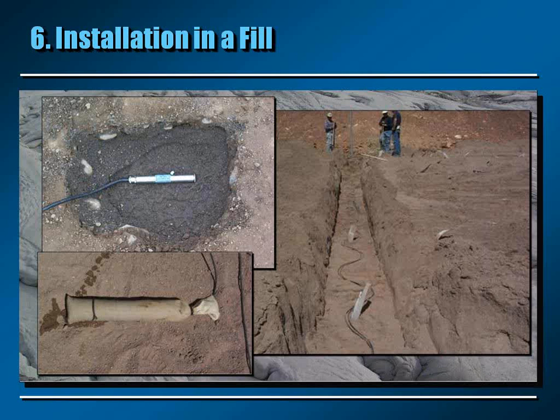You can put it in a canvas bag, that we call it. But it depends on the type of soil in which you are installing the piezometer. And at the right side picture, you can see the cable. There are some loops in the cable.